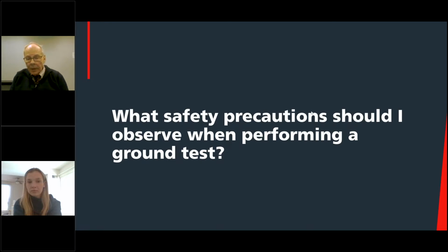However, the test item, which would be now, if you're on an isolated ground somewhere on a construction site that hasn't been energized, you really have very little to worry about. But on the other hand, if you're testing to an energized site or something that's actually connected to the utility, your problem there would be if an event occurs on the line somewhere. There's a lightning strike 2 miles away or something like that, and there's fault clearance going on, and you're connected to the ground and you can be part of that path.